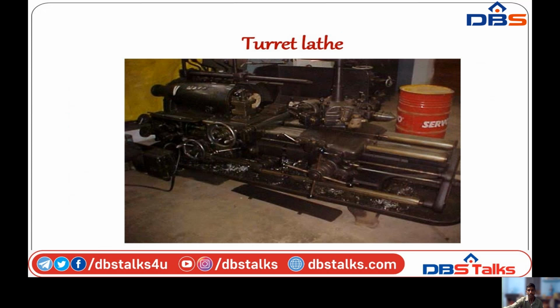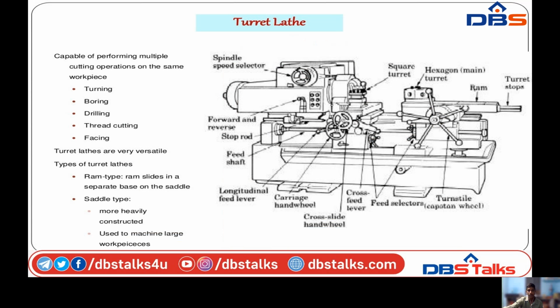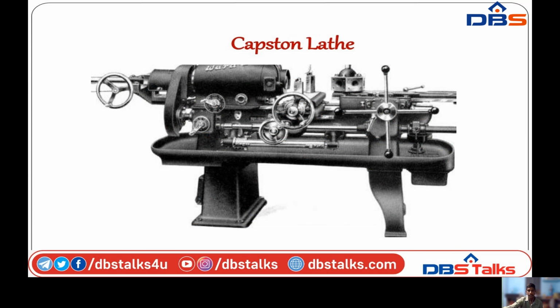This is an example of a turret lathe machine, the figure of a turret lathe machine. In the center carriage position I am showing the tool center, where we can fix a drill bit. Reaming, drilling, tapping and similar operations are performed by using a turret lathe machine. This is the schematic diagram for a capstan lathe.